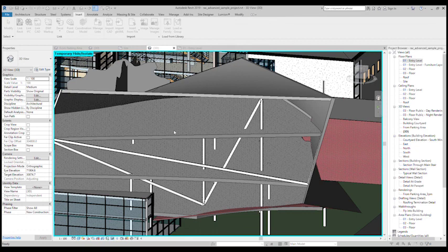Let's add a few wood columns. So I'm going to add a glulam column and just a normal dimensional lumber column. Sometimes when you load columns inside Revit, you can tell Revit which families to load. So these are the types of default thicknesses and sizes. You can make your own ones later, or you can select a preset couple of them. Let's say I need a 64 by 89, I need an 89 by 235, and I need a small one, a 38 by 64.